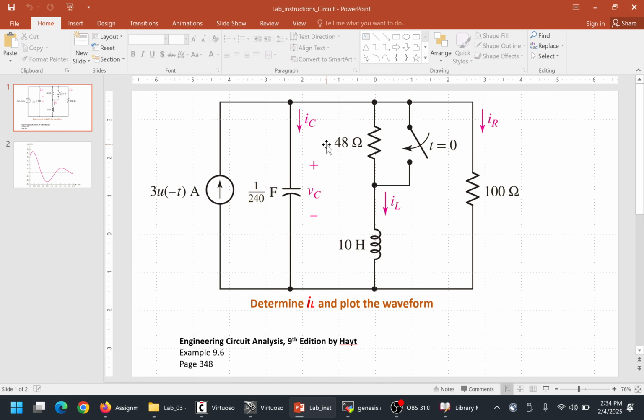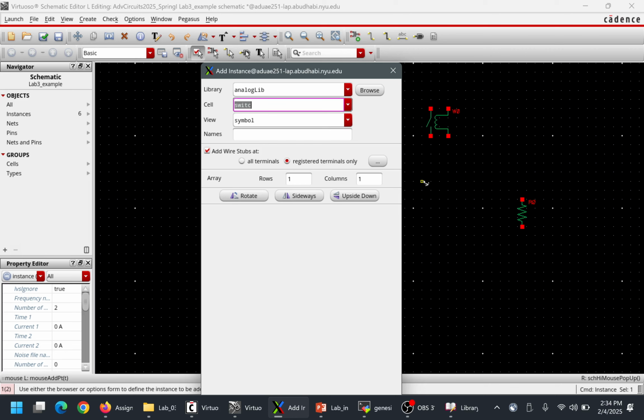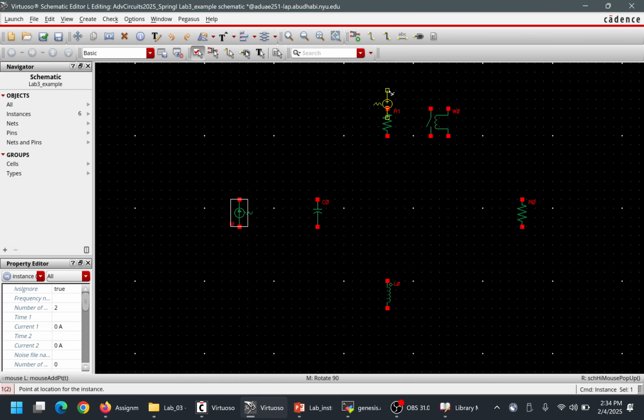So we have to use a piecewise linear source which we can program, okay, how and when it should turn on and when it should turn off. So we have the capability to program the piecewise linear sources, and you will see in a minute what that means. So I'll go into the instantiate and I'll bring voltage source again like I, and then piecewise linear. So that's my voltage source. All right. So before connecting, let's wire the circuit first.